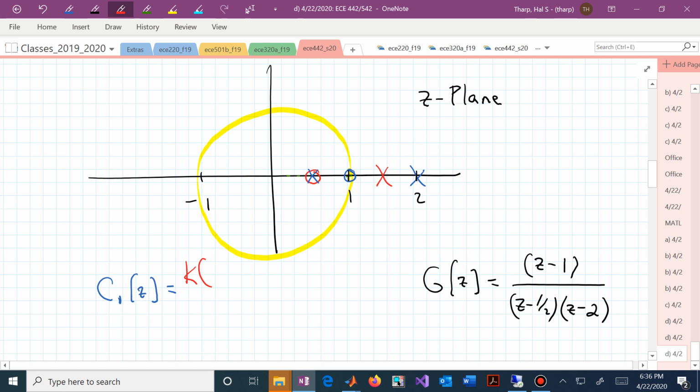We can always cancel poles or zeros inside the unit circle. So now I've canceled a pole in our plant at 1/2 with this 0 factor, z minus 1/2, in our controller. And I've introduced an unstable pole factor in our controller. Again, I'm sort of going back to two bads may actually make a good. And what's the root locus of this look like? Now you can effectively forget that pole-zero cancellation in thinking about sketching this root locus diagram. That is no longer there.